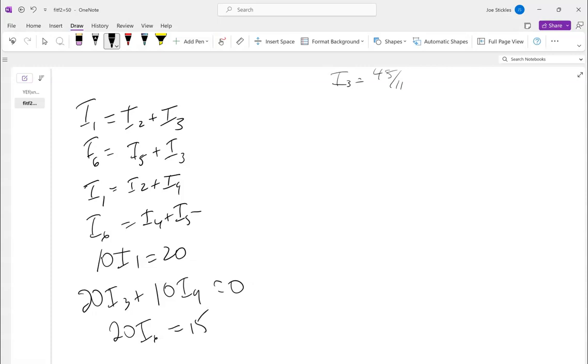So if I switch back over to the computer here, there should be 7 equations we got out of that, right? We had 4 nodes and 3 circuits in those nodes. Hopefully we have enough information to solve everything now, because now we actually have an overdetermined system, don't we? Now, it shouldn't matter if you have overdetermined. The reason why it shouldn't matter is because even if you have overdetermined, you should get a row of zeros at the bottom, or how many rows of zeros you need to make your matrix square. You should get an exact solution out of each of these if you're doing them right.